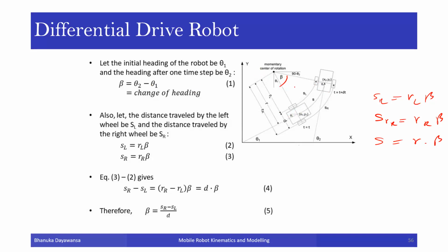And you can basically equate these two together, this one and this one. So if you try to derive, 3 minus 2 is basically the curvature created by the right wheel, and deduct the curvature created by the left wheel, you will get this small curve, whatever is created by the entire robot.